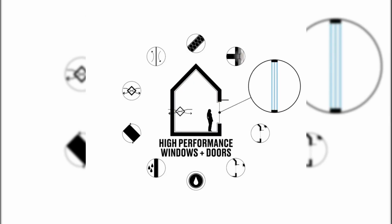4. High-performance windows and doors. Every window or door opening is essentially a breach through the insulated, airtight wall assembly. The performance of the window or door unit and its integration into the wall is vital to preserving the building envelope's integrity. So, we will use windows which have thermally broken insulated frames, warm edge spacers, triple glazing, and low emissivity coatings. They prevent condensation, block drafts, optimize solar gains, and support the overall air barrier.